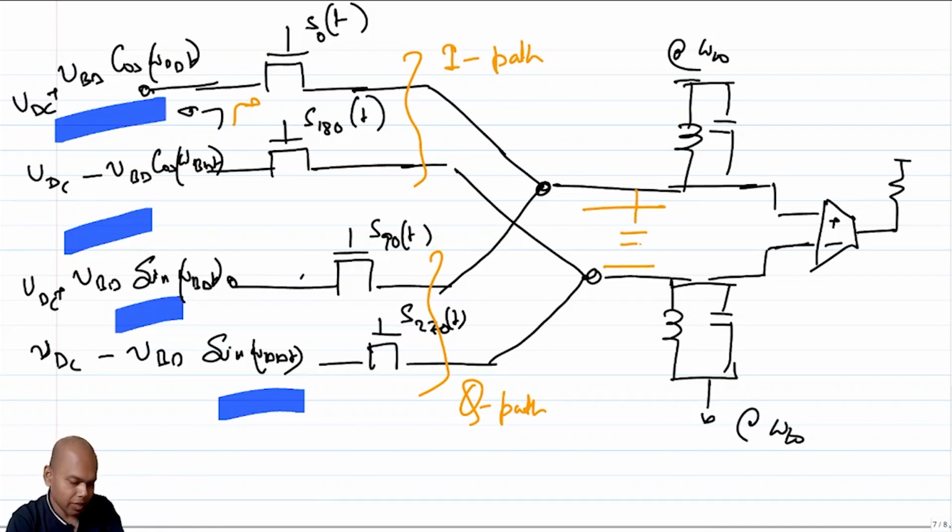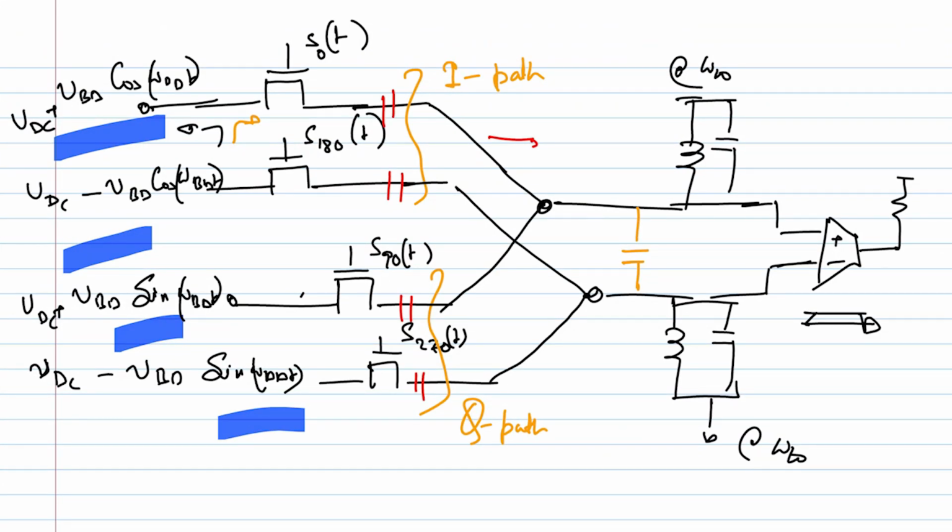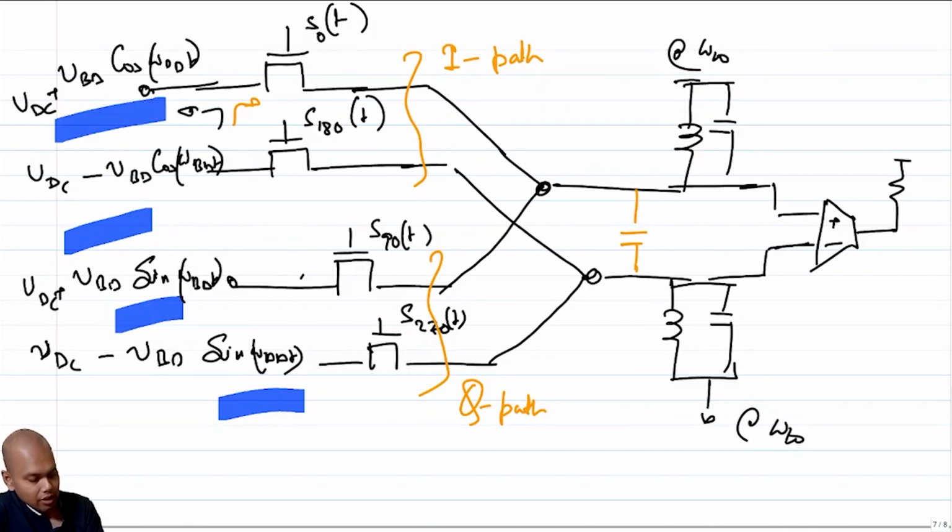So you invariably have some capacitance between these two lines. The moment you have this capacitance, they almost always couple, which means that you do not get perfect image cancellation, or you do not get a scenario where the image is nulled, right? So if somebody is looking to design an IQ upconversion mixer, you have to be very careful with this coupling. Otherwise, you will get a fairly non-negligible amount of signal at the image band, right? Which will not be a good thing to deal with.